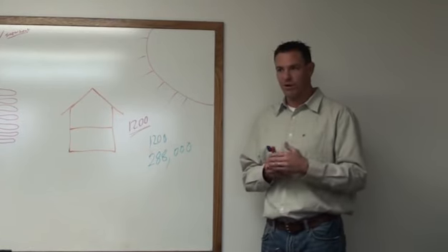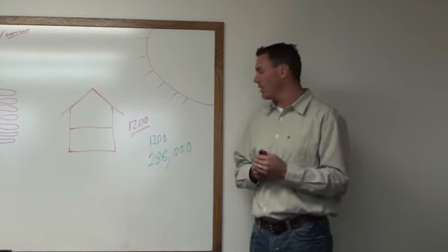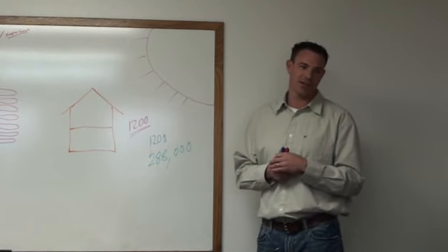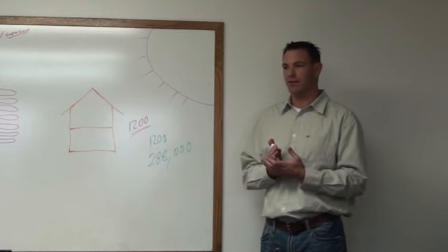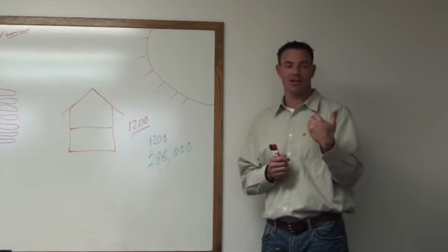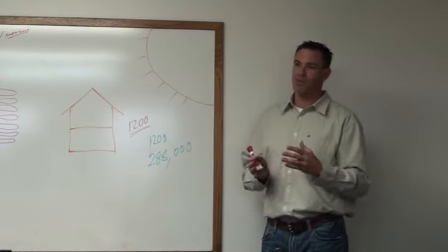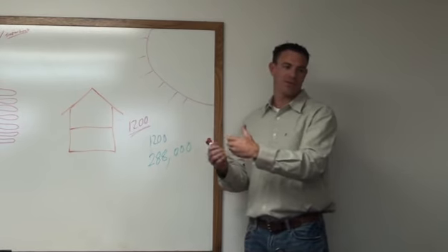a 12,000 BTU unit, or a 1-ton unit, is sized roughly for a 400 to 600 square foot room. Okay, the windows all have to be shut, because if the window is open, we're going to be absorbing additional energy from the sun. So if you've got the window open, you're not keeping up with the thermal mass, you're keeping up with the thermal mass and the outdoors.